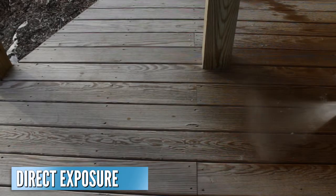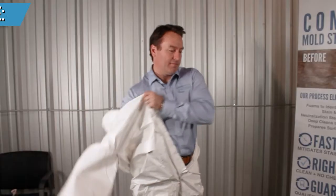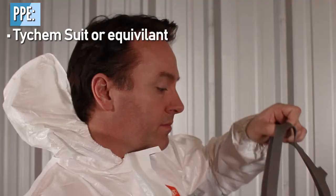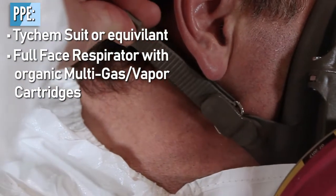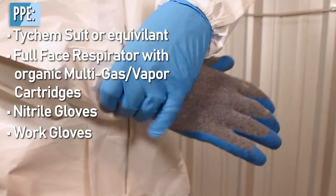Let's discuss personal protection equipment. Liquid treatment constitutes a direct exposure level where chemical contact is expected and/or unavoidable. For skin protection from direct exposure, use Tychem QC suits or equivalent. For respiratory protection, use the multi-gas multi-vapor cartridge for your full-face respirator. Make sure that your mask has been fit tested. Use nitrile gloves for chemical resistance and a work glove to prevent ripping of the nitrile glove.